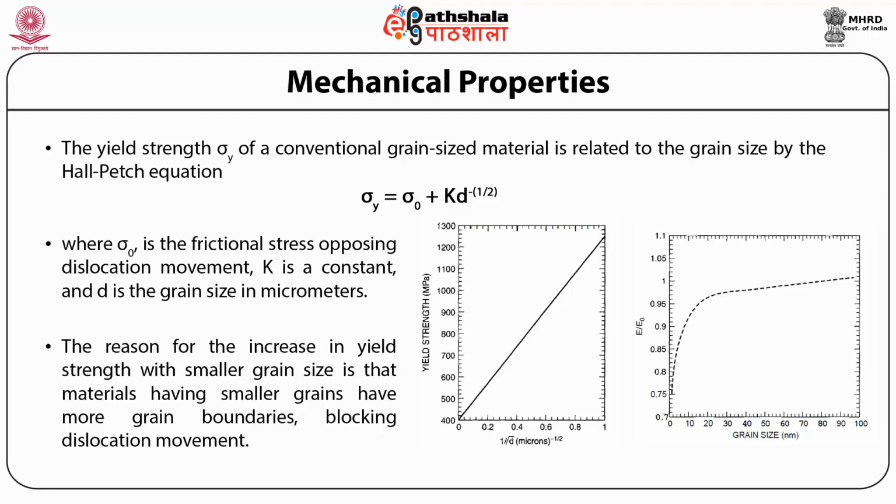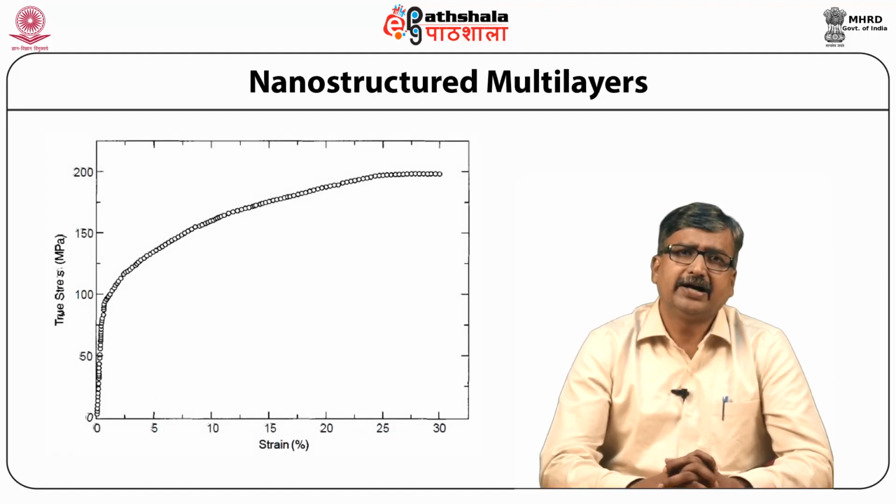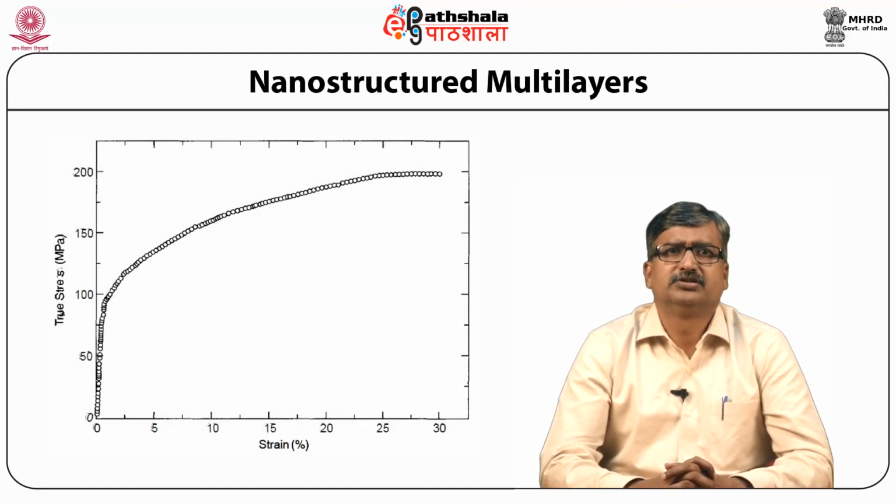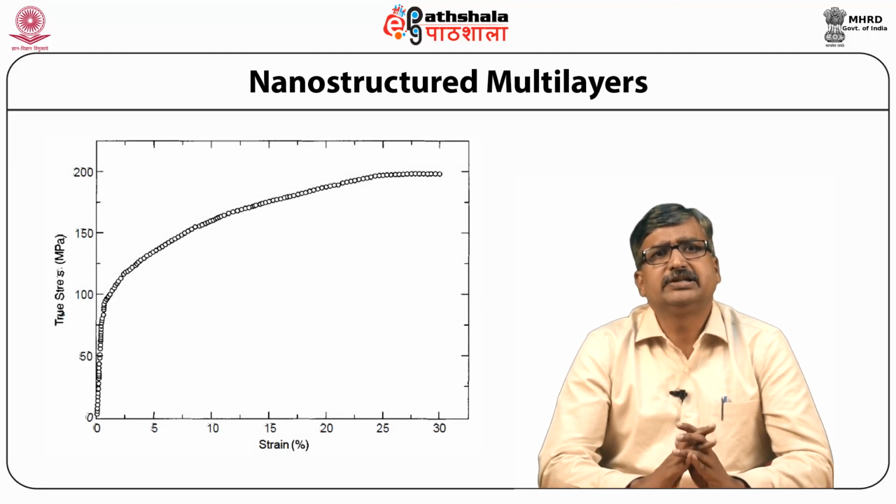mechanical properties. In general, the results of ductility measurements on nanostructured bulk materials are mixed because of sensitivity to flaws and porosity, both of which depend on the processing method. Another kind of bulk nanostructure consists of periodic layers of nanomaterial of different materials, such as alternating layers of TiN and NbN.